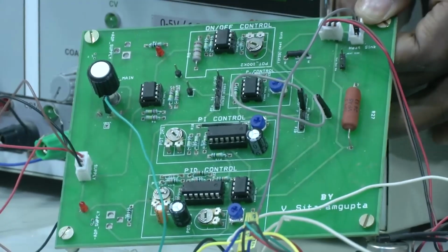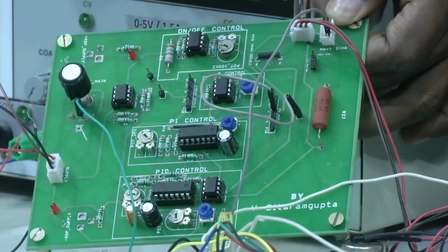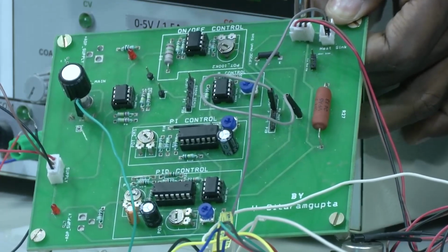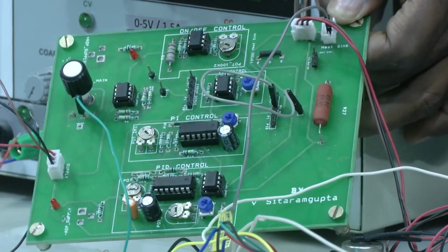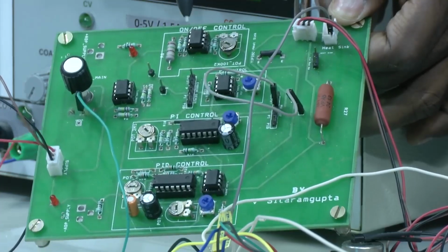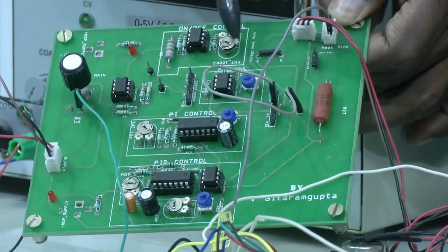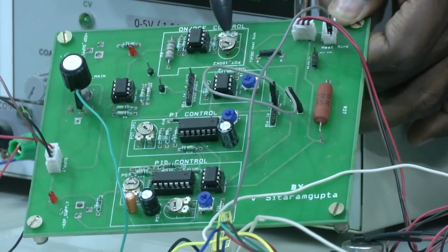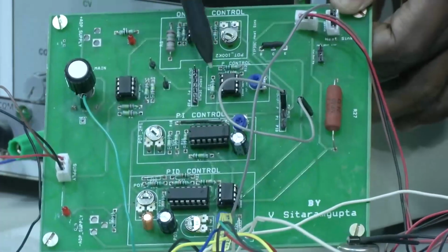If you recall, we have used 3 resistors R1, R2, R3, right, all 3 resistors we can see, and we have used the on-off controller with the signal conditioning circuit, right. Since this is a TL082 with a single op amp, we can design the Schmitt trigger plus signal conditioning circuit. The attenuation is completely done by using this resistor pot, right. Below this we have a P controller.